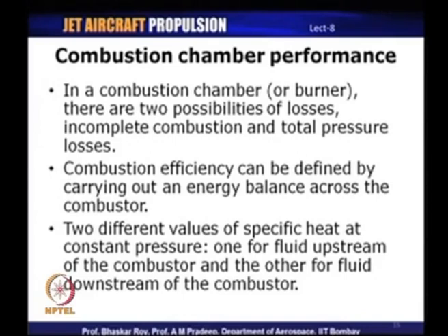the only thing that we have to remember here is that in a combustion chamber, we will no longer be using the same specific heat across it, because the temperature differential between the inlet and exit is substantial, and so we can no longer use the same specific heat at constant pressure for the inlet and exit. So, we are going to use one specific heat for the fluid which is upstream of the combustor, and another value of specific heat for the fluid which is downstream of the combustor.